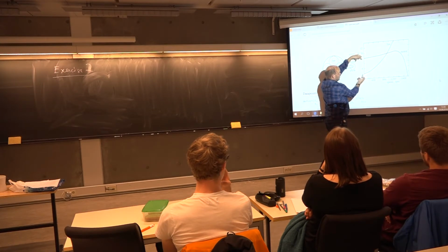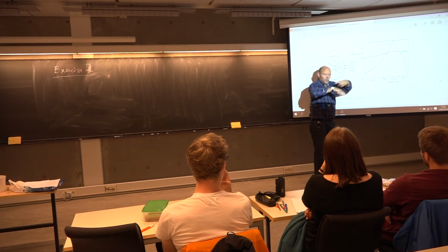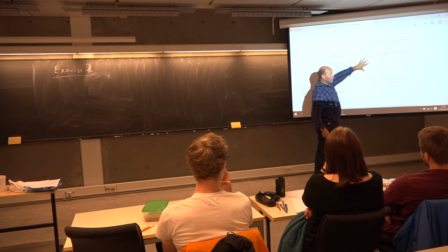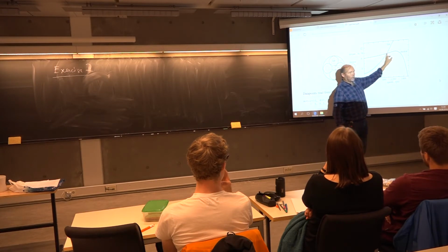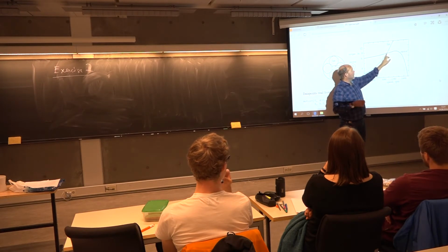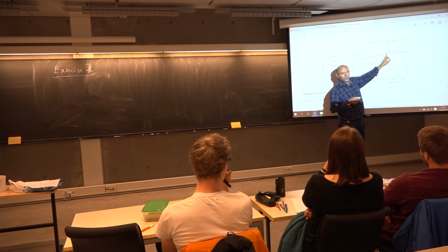So this net torque is going to speed up the system. It's going to start to move, and it's going to rotate faster and faster until you hit this point. Then you will be in balance. Then all the power out from the motor will be swallowed by the fan. It's in balance, and this is what we call the stable operating point.